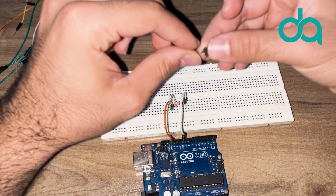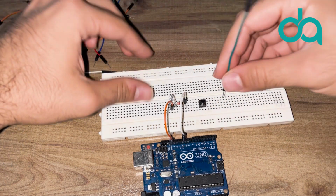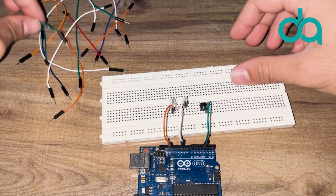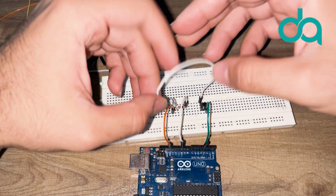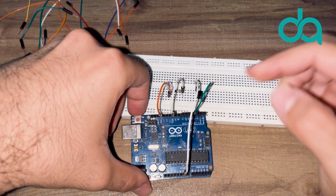And here is the button. Put it on the breadboard and connect one pin to pin 3 and the other pin to the GND port of Arduino, and that's it.